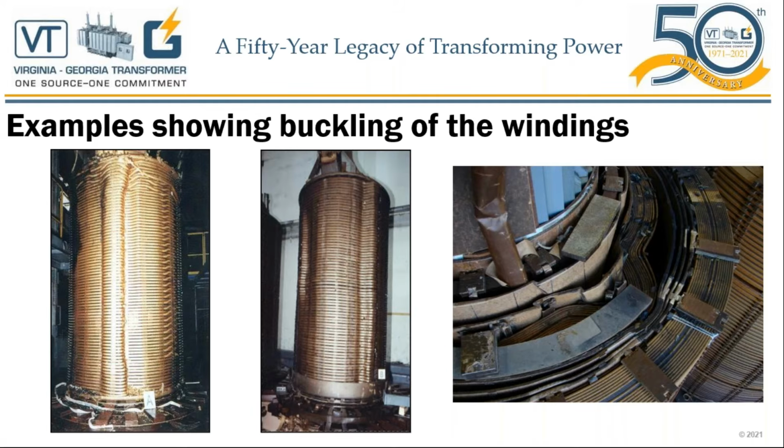This is the very typical buckling of the inner winding, where the inner winding could not withstand the compressive forces, which were trying to squeeze this inner winding towards the core steel, like I said before. If you look at the picture on the right side of the slide, it's very evident how the inner winding has buckled. So now the question you probably have is why? And the answer we will discuss more on the upcoming slides, but I'd like to talk to the picture.